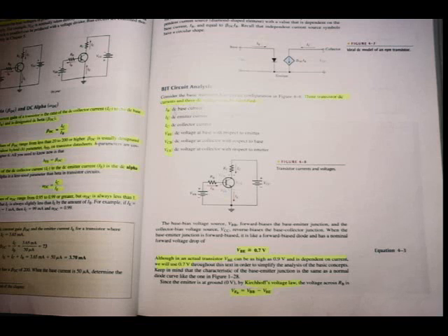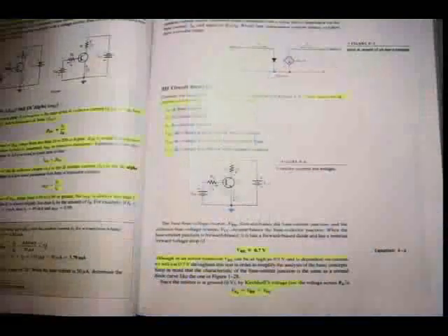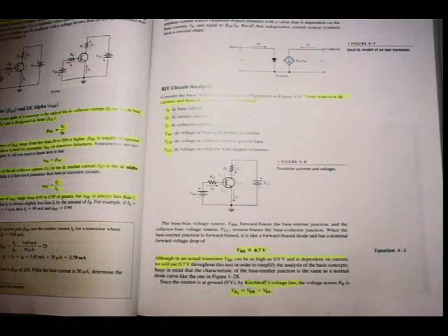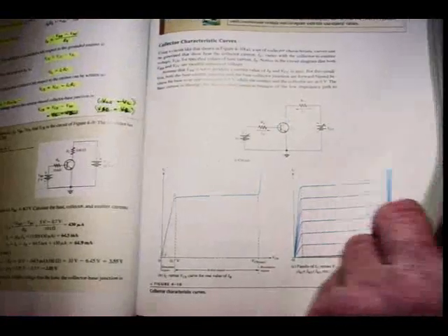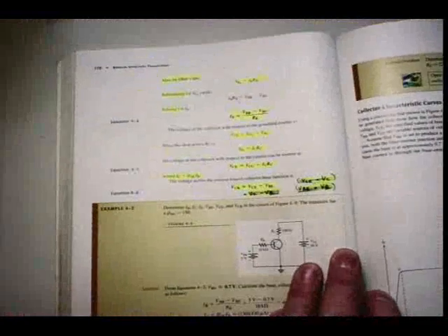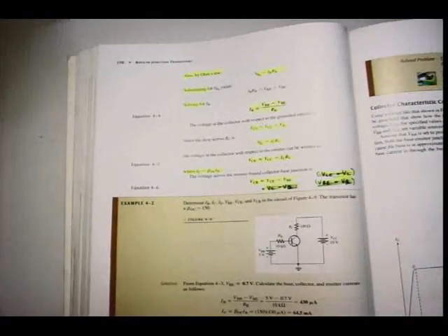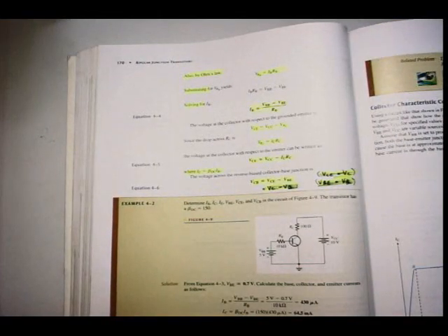Right at the bottom, see there they already mentioned Kirchhoff's law. Kirchhoff's law that you've learned since school, and you've done it in electrical engineering again. You'll do it in electronics again. You will always use Kirchhoff's laws and Ohm's laws in electronics. I can determine that the voltage across RB is VBB minus VBE, as I've explained to you now. Now if we turn the page, also by Ohm's law, I've seen that VRB is equal to IBRB.